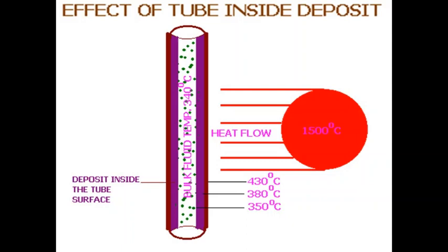That is the point of concern, that the water or water steam mixture is not receiving more heat, but the tube metal is receiving more heat, and as a result its temperature changes due to the scaling resistance given by the scales.